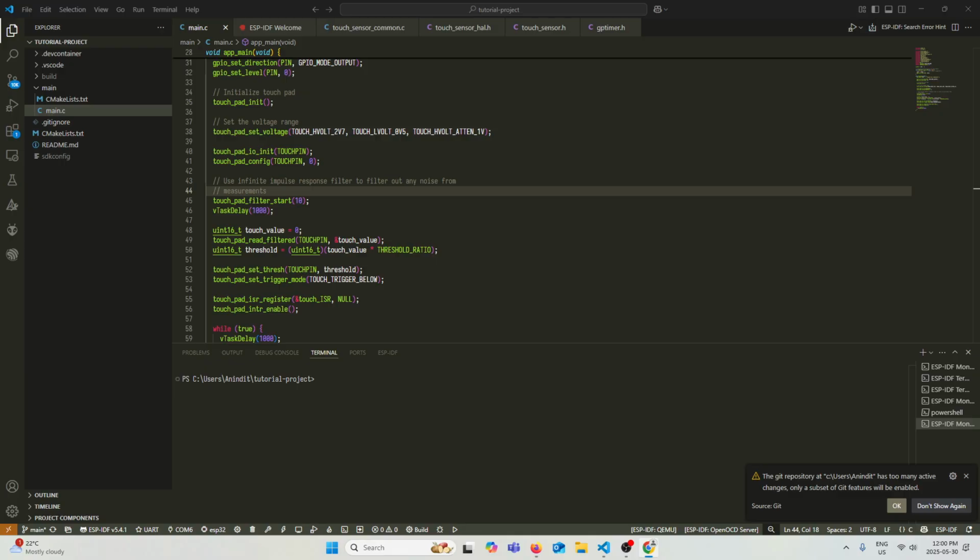Yeah, okay, so again, attenuation will just effectively scale down any analog input that exceeds the reference voltage. But how much it scales down, the video doesn't say. I'm reading a data sheet right now, and it says there's a table of ADC calibration results.